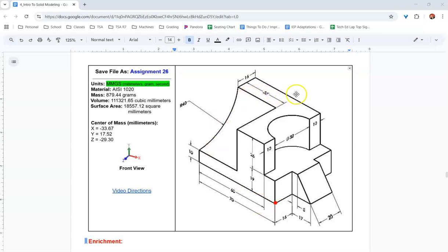While I'm looking at this, I can see an angled surface here, a curved surface there, another curved surface there. I always recommend drawing the shape that's either an angled surface or a curved surface from the side that you will actually see that feature. But in this case, we have multiples of those. It's not just a simple shape, so you have to pick and choose your battles here of what's the best way of doing this.